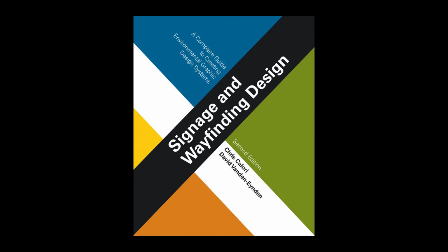Stainless steel. Stainless steel is typically used for sign faces, plaques, cladding, and trim. It's generally too expensive for structures. Another of the white metals, stainless steel is a darker shade of gray than aluminum. Other characteristics include excellent appearance, it's rarely painted, excellent durability, heavy weight and high expense, because it does not rust or rusts minimally, hence the name stainless. Protective coatings are not usually required. See Figure 6.37.